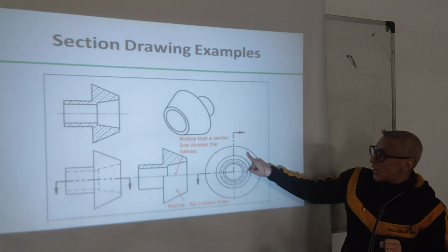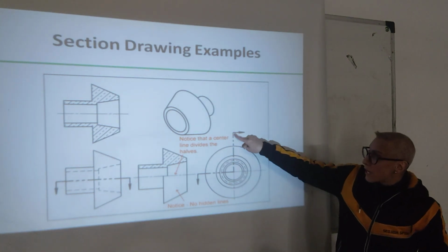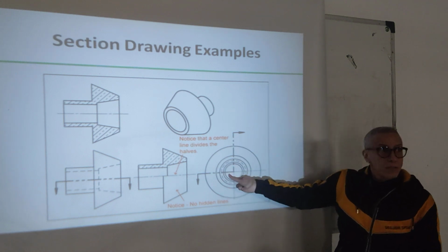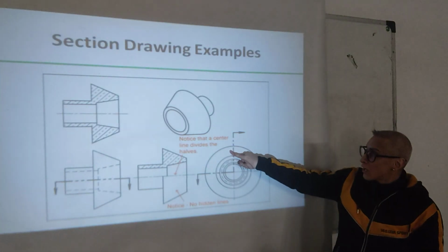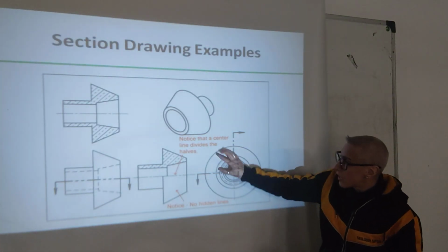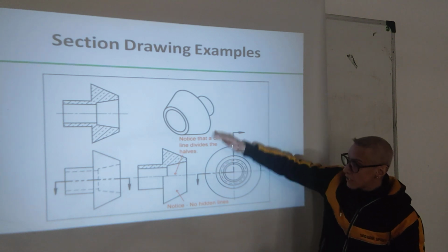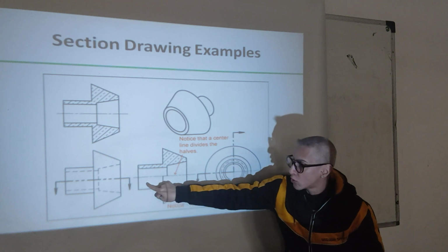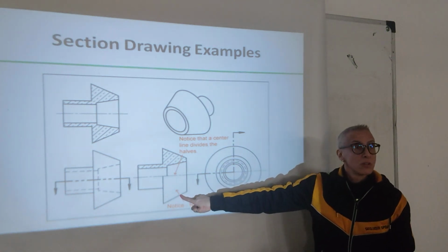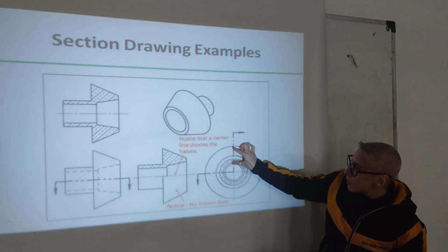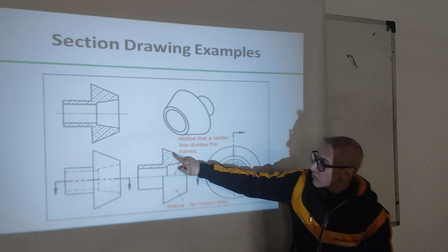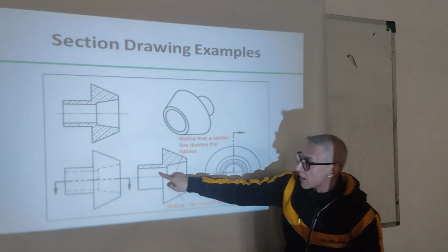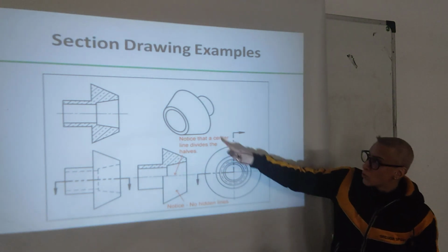Okay? So, now this line is put on this view, and it is half. Okay? So, no need to show this part, because it's the same as this part. So, we will just cut it through like this, and delete this part, and look how it's shown here. This part is shown here, drawn, but it's closed. We don't see what's inside. Only this part here is deleted, and where is the solid material? It's hatched. Where is the empty space from these holes, basically?